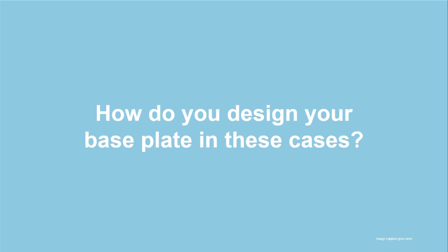So how do you design base plates in these cases where Design Guide number 1 is not allowing this kind of configuration? If you really feel that, with my base plate, I'm not sure if it's rigid or not, how do you design it in these cases?